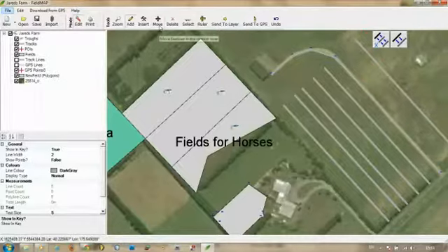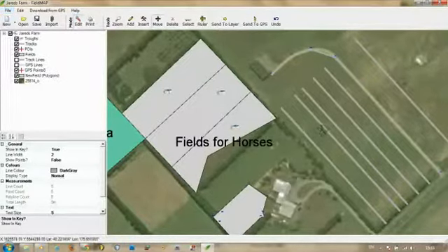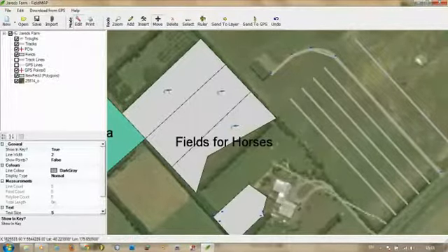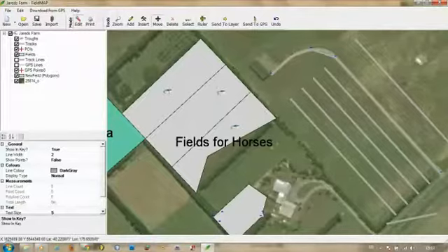You can edit and move your polylines by clicking the Move tool. To rotate a line, select one point and drag. To extend a line on its original axis, hold the Alt key on your keyboard and select each endpoint and drag, making sure you hold the Alt key down as you drag the mouse.